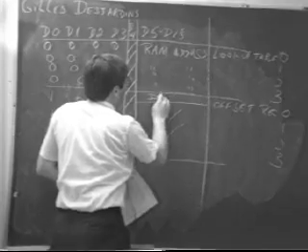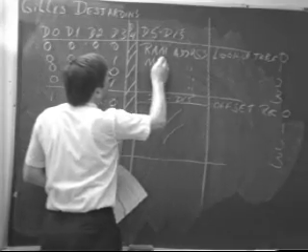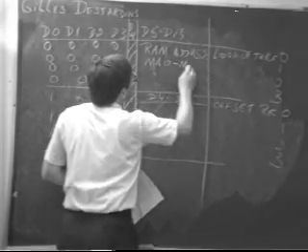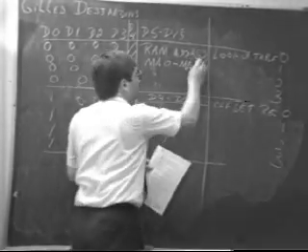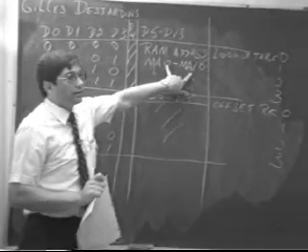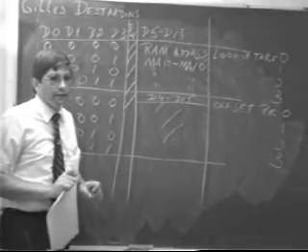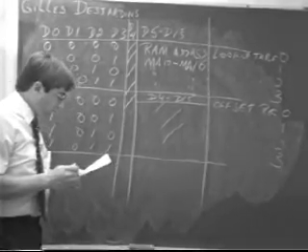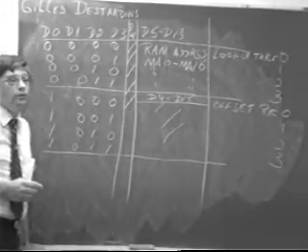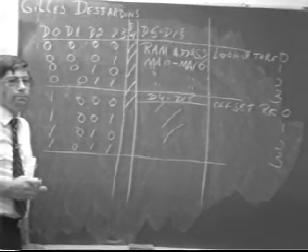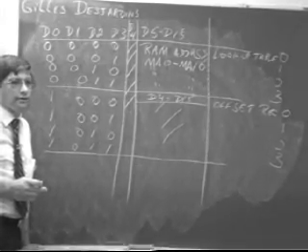Here it is D4 to D15, but for MA it is MA0 to MA10. So we only use 11 bits. You had a question? Well, you have to first address the RAM and then the data is put into it. Yes, correct.